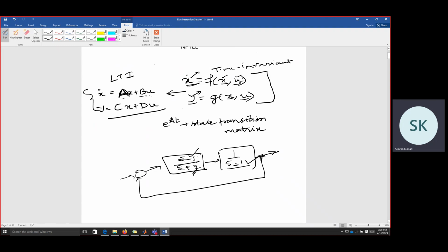Now, due to some perturbation or some external factor, because the plant model that we are having, whether it's a transfer function model or this state space model, is not an accurate one. They are simplified and approximate models of the system. So this cancellation may not be there, and this can lead to instability of internal signals like this U. So this can lead to an unbounded U signal. So in this type of condition, it is better if we have access to state variables or the internal state of the system. So in that case also, this state space representation is good to work with.